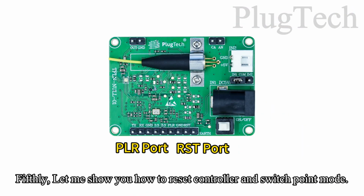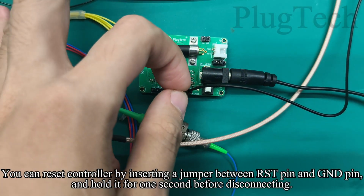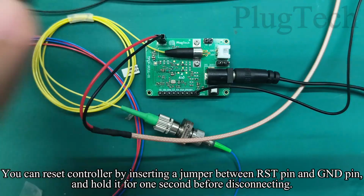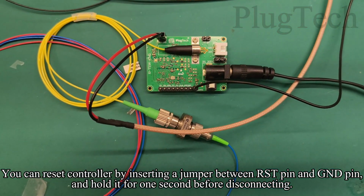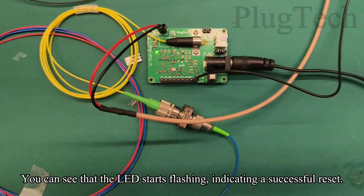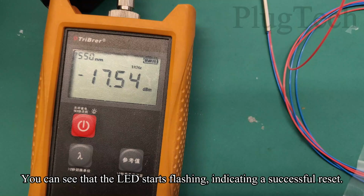Fifthly, let me show you how to reset the controller and switch point mode. You can reset the controller by inserting a jumper between the ST pin and the GND pin and holding it for 1 second before disconnecting. You can see that the LED starts flashing, indicating a successful reset.